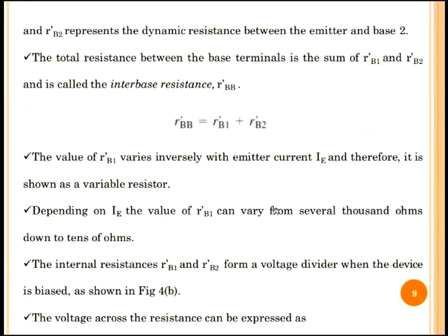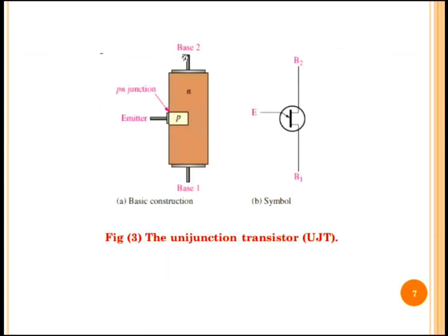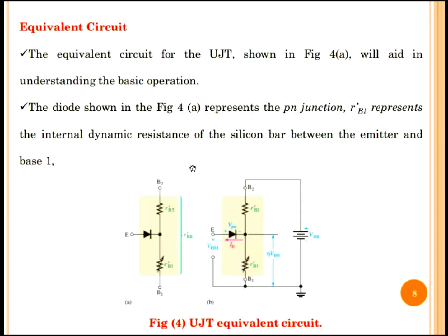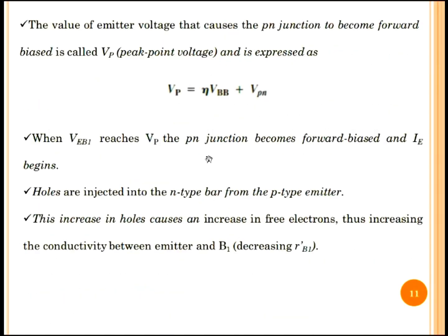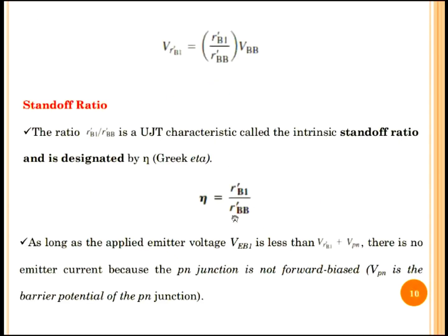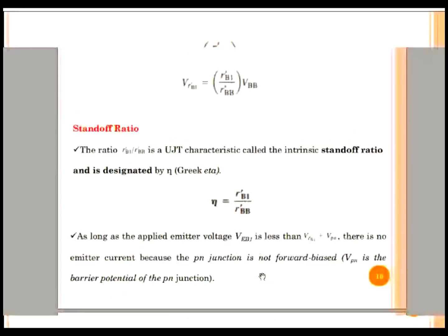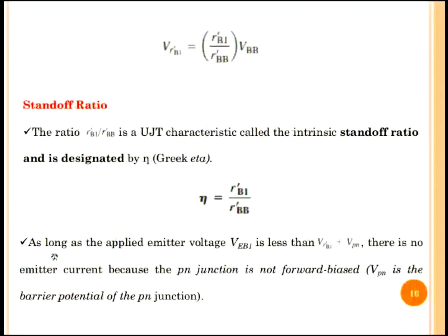Interbase basically means we have a base, right? There are two bases, one and two. So the resistance between these two bases, we call it the interbase resistance, right? That's how the name comes. If you divide by that interbase resistance, you will get the intrinsic stand-off ratio. As long as the applied